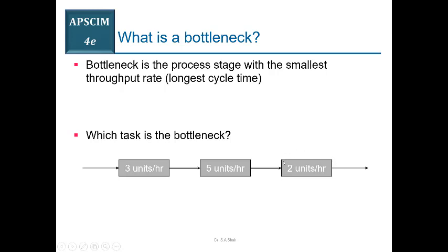And whatever the bottleneck is becomes the cycle time and production rate of your system as well. So now the capacity of this system will depend on this bottleneck station, and whatever the cycle time or the rate of this bottleneck is, that will eventually become the production rate or the throughput rate of the whole system as well.